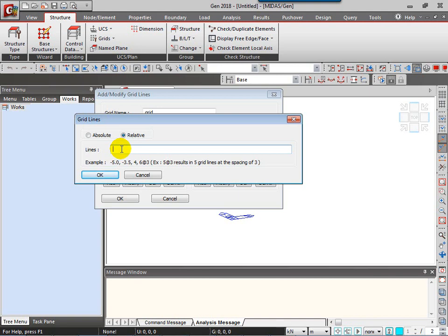I'm making a simple structure like shown before, so we're having 2 numbers of spans at 0.6 meters each, then 1.3 meters apart. We have the same spans 3 times, so I'll just select this, copy and paste it twice. And lastly, we have again 2 at 0.6 meters span. So with a comma, you can provide the next spacing,